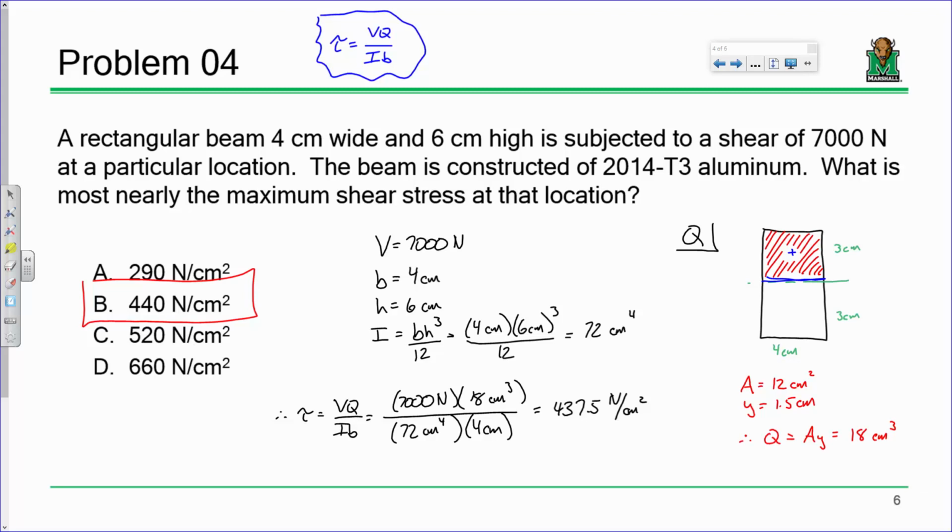So it's a function usually of statics and the cross section. What do I mean by that? Well, if I have sigma equals P over A, so I take the force divided by the area. The bigger the column gets along its cross section, the lower that stress is, right? So there's that. What I then say is, okay, if I got stress, I can then say, what's the strain? Now, how do I get from stress to strain? What do I need?